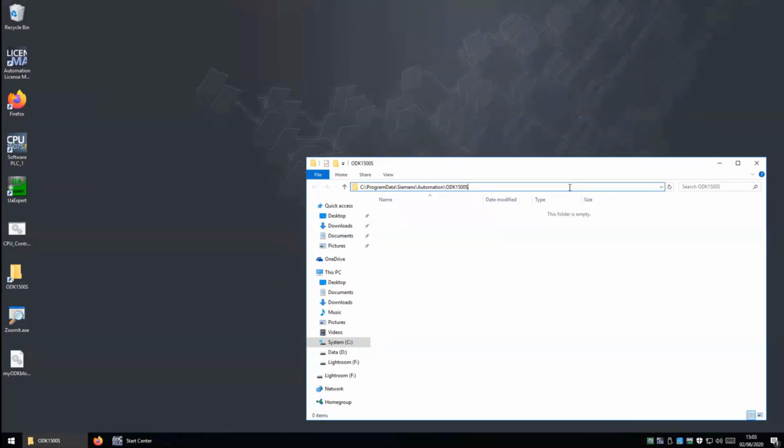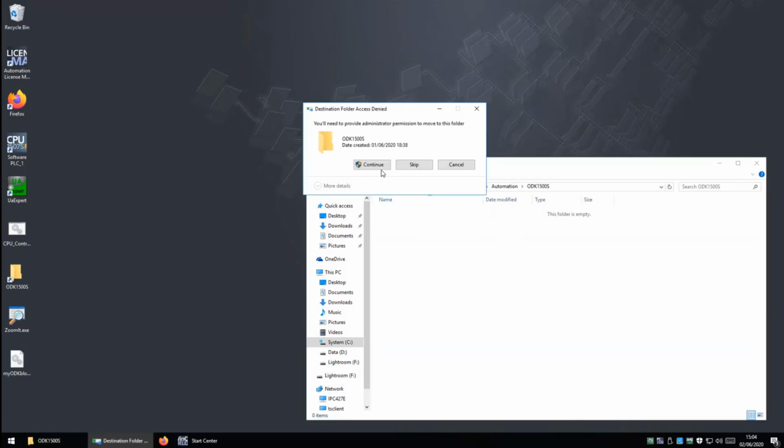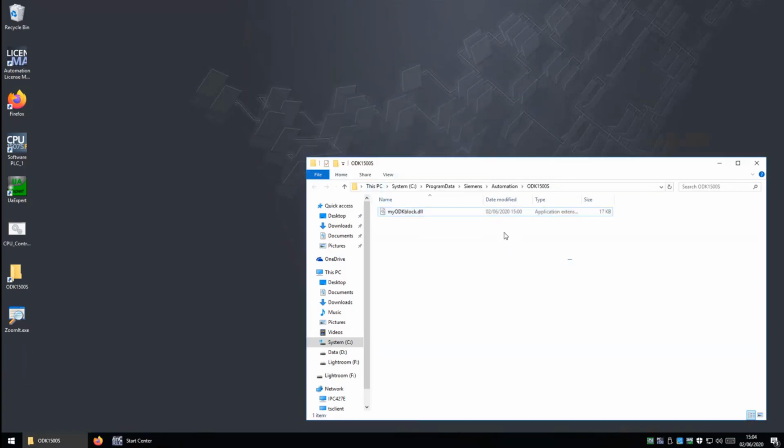And what happens with this directory is Windows scrapes this directory for DLLs, and Windows also listens to the software controller. So if you imagine this is the conduit for the DLLs that get loaded. So if we pop this into here and click continue, we now have our new DLL containing all our C# code ready to be controlled from the PLC.